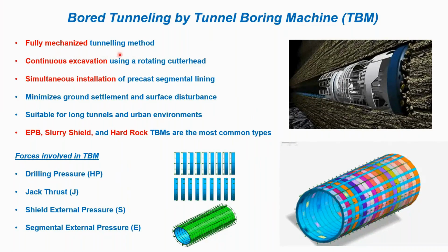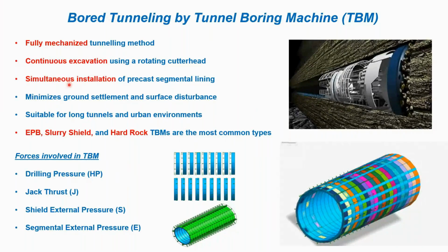In this, excavation is carried out continuously using a rotating cutter head located at the front of the machine, as shown in this figure. As the machine advances, precast concrete segmental lining rings are installed immediately behind the TBM, allowing the excavation and support system installation to occur almost simultaneously.